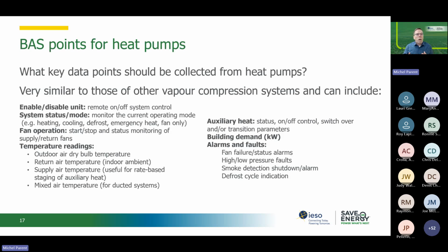In terms of the minimum number of points you want for your heat pumps, they're very standard. A heat pump is basically an air conditioner working in reverse, so there's nothing I can tell you that you shouldn't already know, other than maybe the 4-way valve and the status of the heat pump. Is it in heating mode? Is it in cooling mode, defrost mode, and some are in heat recovery mode if you've got a VRF or a 4-pipe heat pump? So the points are pretty standard, but you will add the status, the mode, and if at all possible, make sure you get live building demand, because it will become a control point in a lot of your control strategies.